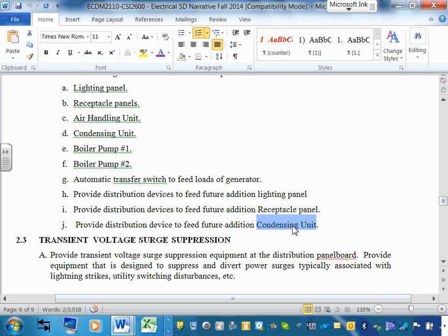Typical, one room, in a building like this. But the bigger the building, the more electrical rooms you have. What they typically do in a major, huge building is have one electrical room in the basement where the service comes in, and then every floor will have an electrical closet with one or two light panels in it, fed from the basement directly, feeding the receptacles, the lights and the mechanical equipment on that floor, and they keep going: second floor, third floor, fourth floor, and so forth.